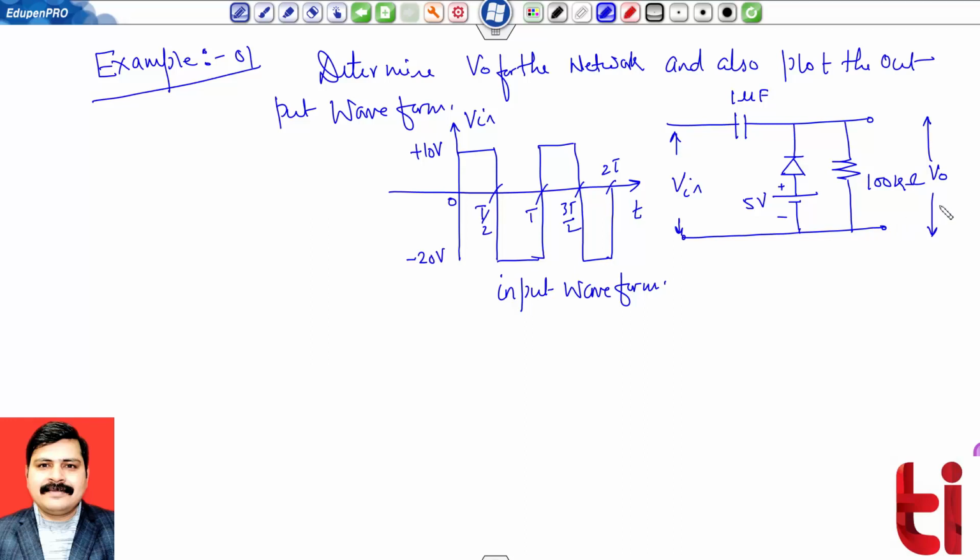Assuming there is no issue of charging, as the frequency of the signal is not given, for simplicity one can calculate the value of tau, and this will be equal to R into C. So 100 into 10 raised to power 3 multiplied by 1 into 10 raised to power minus 6.